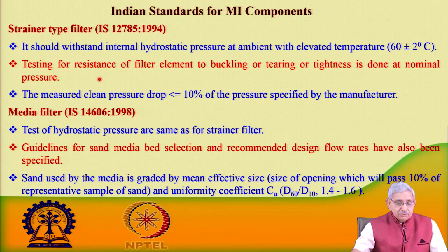Strainer filter should follow this particular guideline, and these are the set of values which have been recommended. The filter element should not undergo buckling or tearing under pressure.